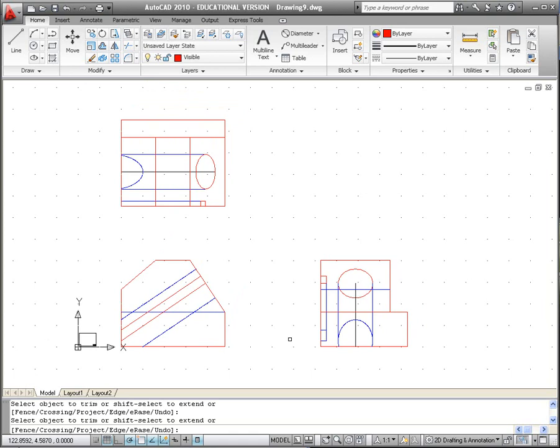Now you may be wondering about the next part. How do we get this whole thing set up correctly? Because there's our printable paper. Well, if you recall, these dimensions that are like 30, 40, 50-ish, what they are is millimeters. So sometimes you'll have a metric drawing that you need to scale and put on a piece of paper, and this is one way to do it. There are other ways to do it using layout space, but this is one way, since it's supposed to be small enough to fit in the title block.